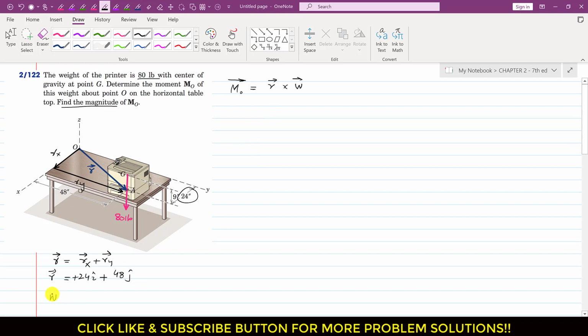So this is our moment arm. And we can write the weight as a Cartesian vector as well. The weight has a magnitude of 80 pounds and it is acting in the negative k direction. So this is the Cartesian vector representation of that weight. Now we can write that the moment about point O due to that weight is equal to 24i plus 48j, this is our moment arm, cross that weight, which is minus 80k. Now we can use the determinant method. So this is i, j and k, this is 24, 48 and 0, and this is 0, 0 and minus 80.